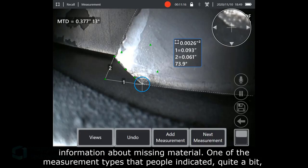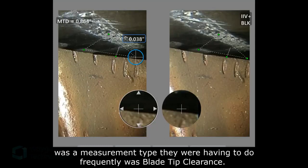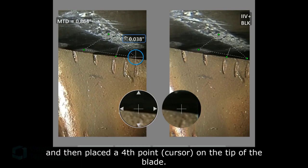One of the measurement types that people indicated they were having to do quite frequently was blade tip clearance. And in this case, here's a stereo, or actually a Real3D stereo image where somebody on the left-hand side had placed 3 points to establish a mathematical plane on the shroud at the top of the image, and then placed a 4th point on the tip of the blade.